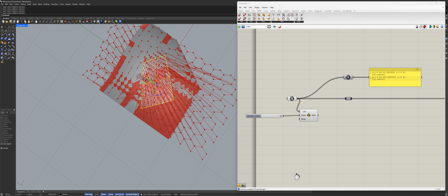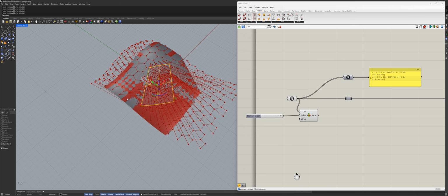Every single surface is unique. Every basis function for every surface is unique, and the properties for that are unique. Its directions, its density, its orientation, everything is unique. You can't construct a uniform domain. And trust me, for the last 20 years, a lot of our smart people tried to do that, tried to change the concept of the NURBS so it will be more friendly to parametric, and they all failed, to be honest. So the previous big hit was T-splines in 2008 when this concept was supposed to solve the T-junctions, and it kind of did that, but it was not accepted by the industry for multiple reasons.